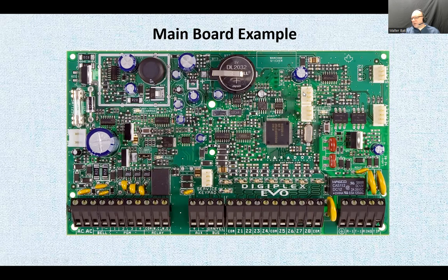Very rarely are you going to use these connectors. That's for the external dialer and whatnot. You know what, I've never used these in so many years that I have done this. Service keypad, that is if you do a lot of service on the systems and you have a keypad in your van, so you don't have to go to somebody's bedroom or basement or wherever the keypad is to do some keypad programming, then you can just plug in that keypad right here. Now, let's take a look at some of the peripherals here.